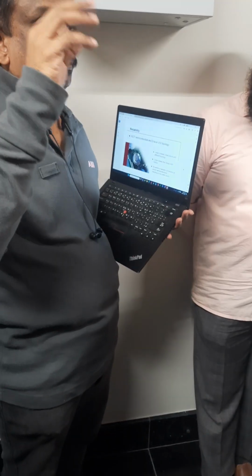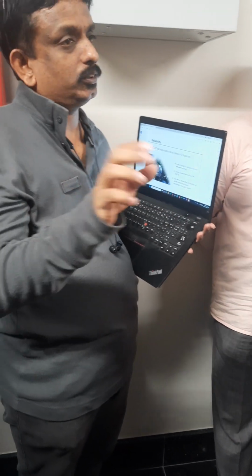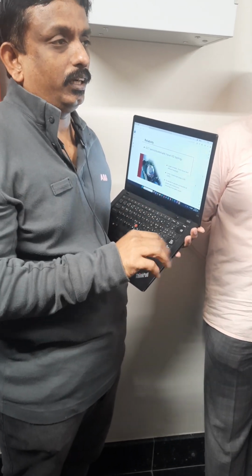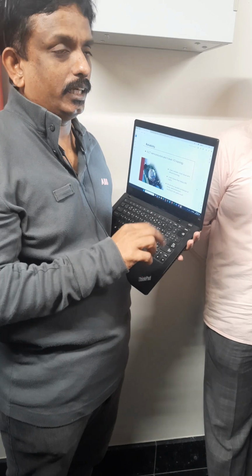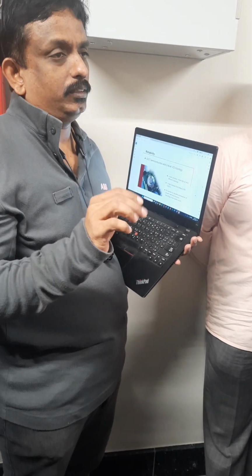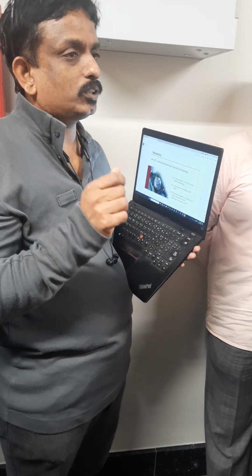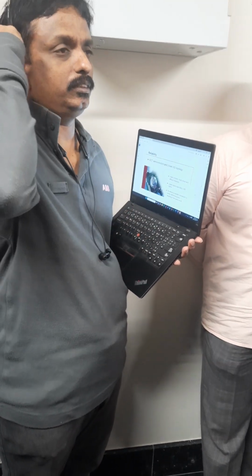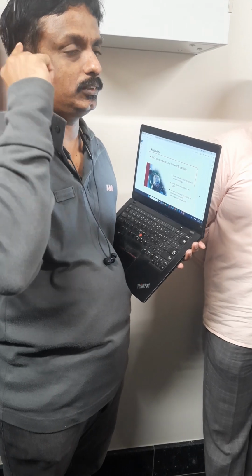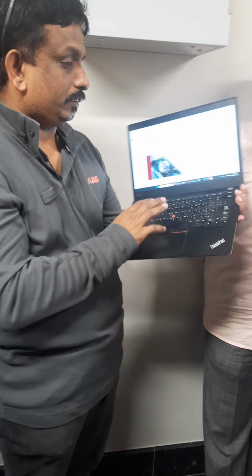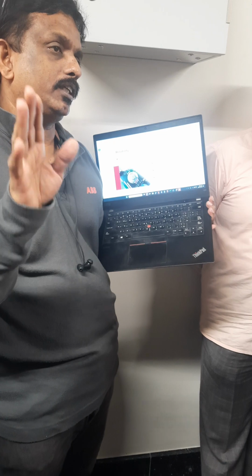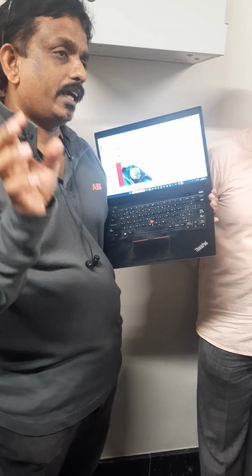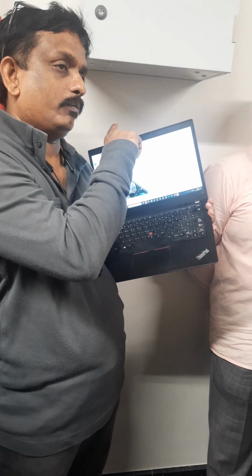During running, you should not do any of these activities. It should be off, then open and clean, then the breaker turned back on, and run. Then there is a control supply; if you disturb the control supply, it will give a trip in the switch gear. And one more thing, all protection for the drive is the main breaker. Any fault in the drive will operate the breaker only.